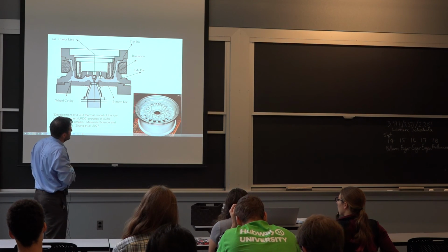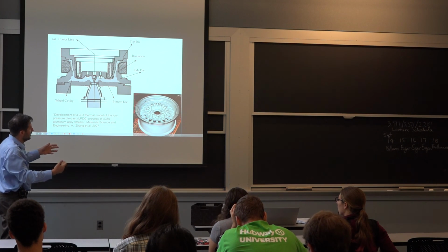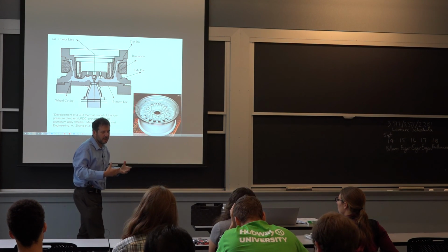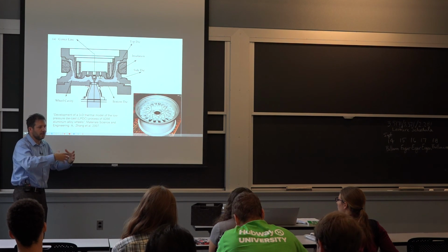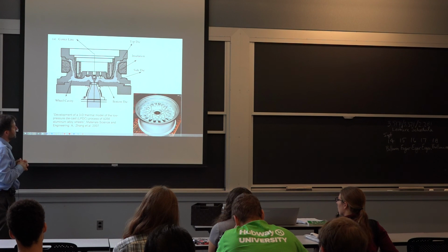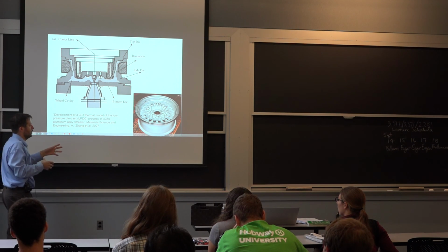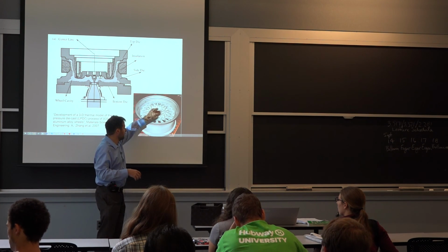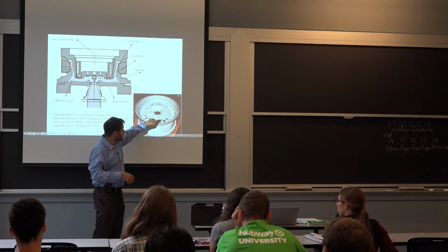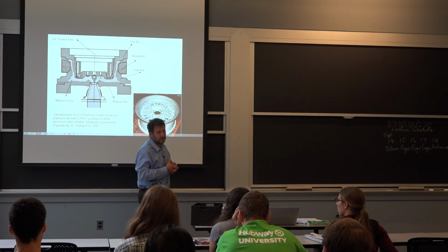There are other plastic parts in injection molding where you may decide that you're injecting from a more central location, but then when two zones merge, you have a mold line. So there's always a trade-off, but in this case, that's one thing they avoid. They really avoid the interface by having everything grow from the center outward, but it needs a lot of flow. You need the liquid metal to get all the way to the outside rim.